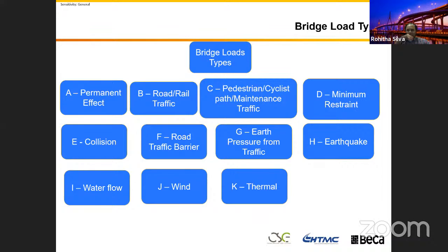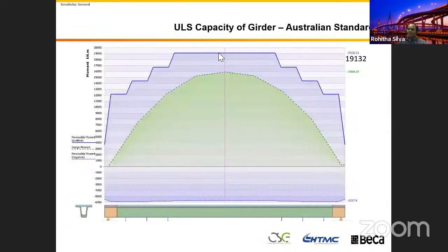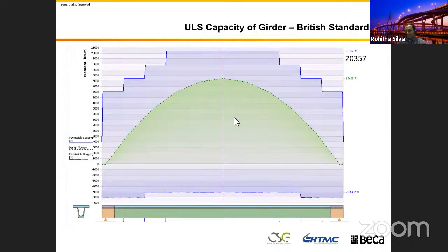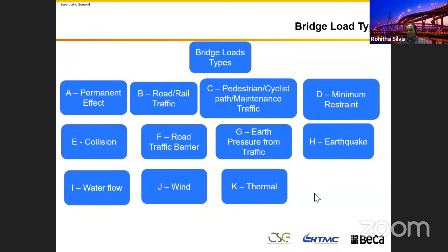Then your answer is going to be, yeah, don't worry, mate. I did my analysis using MIDAS. I got this bending moment diagram up here, down there. It's in the middle here, because my actual bending moment is much less than this. You can show this diagram. You can see this is the capacity, this is the load. So fine, don't worry about the load case, right? That is not a structural engineer's answer.